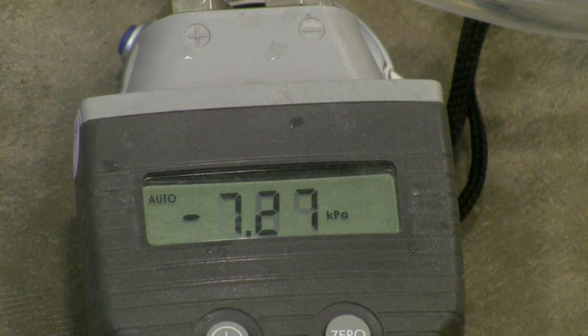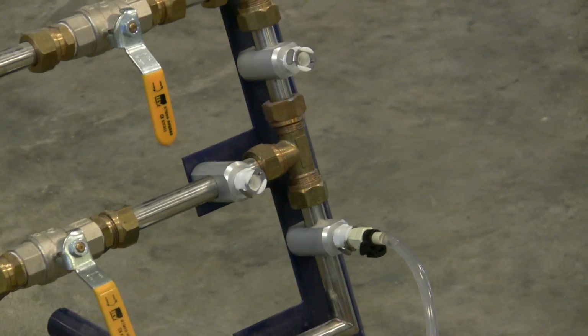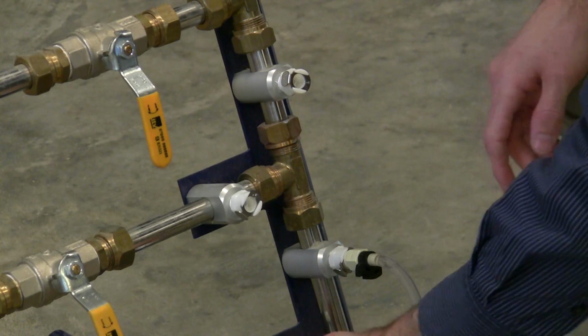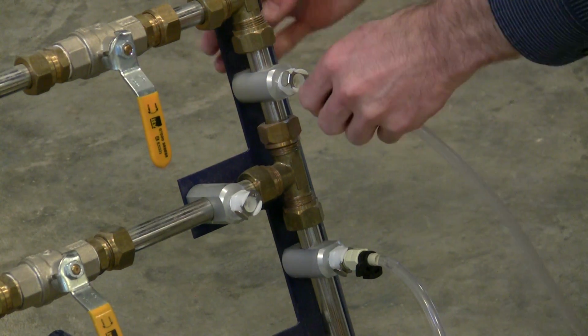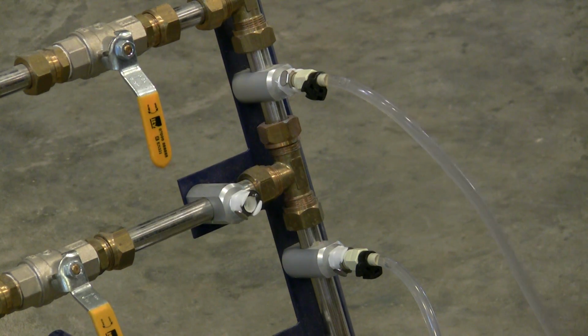90-degree T is next. 90-degree T, we're already plugged into one of them. Let me go plug in the other. All right, I'm going to visually inspect the line to see if there are any significant air bubbles that need to be purged. Again, it looks like, oh, I do see one. Actually, I see two, so I'm going to go ahead and purge those.